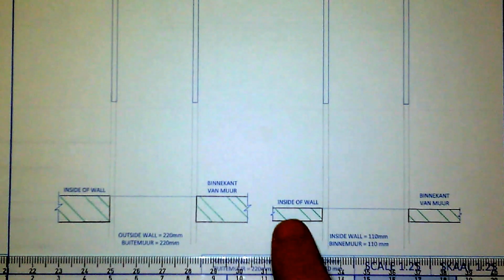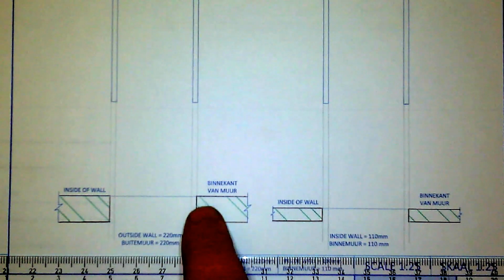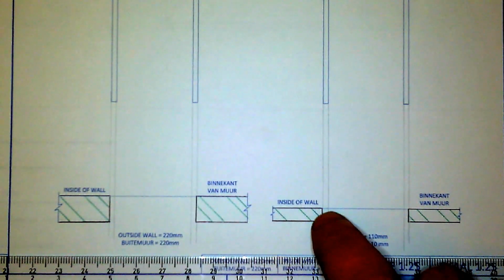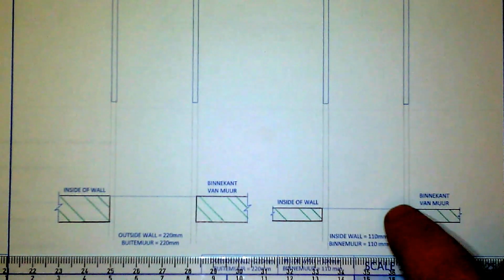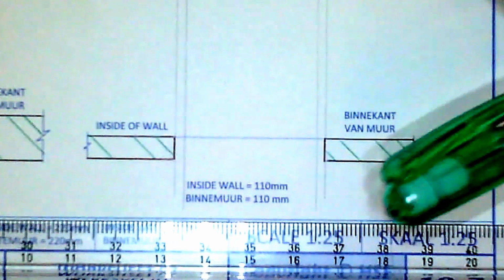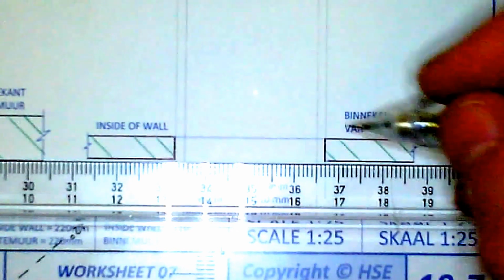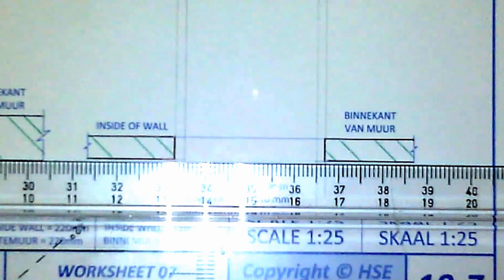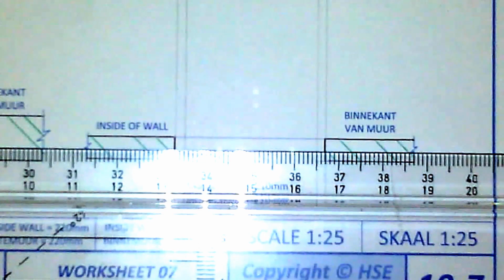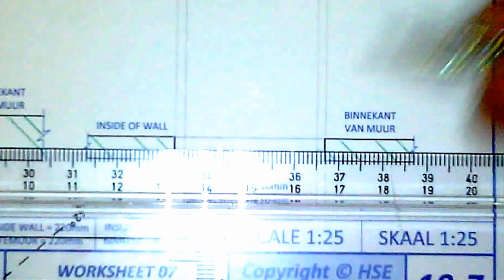Right, so now you can see that the walls are actually done, and I can focus on adding the frame for the doorway. Going to the inside door first, I'm just going to add the slight rebate on each side that we're going to need, or the frame of the actual door, in order to fit the door inside. Alright, so to do the frame of the door, I'm basically just going to use the thickness that I've projected from my front views, and I'm going to divide it into a small block if we're halfway into the wall. Okay, so it's going to be very small, so you have to work very accurately here.